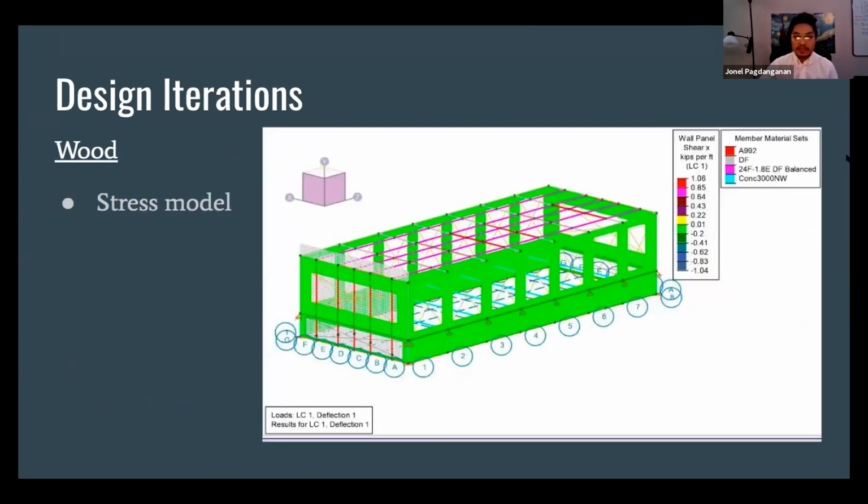So the structural analysis of the multi-use building will be using RISA 3D software for both the concrete and timber materials. The color green means the member passed in deflection. A value lower than 1 is acceptable. The color red for a highlighted member indicates that the member failed, which refers to a value of 1. The model passed deflection for the walls and framing for both the concrete and timber material with a value between 0.01 and -0.2.